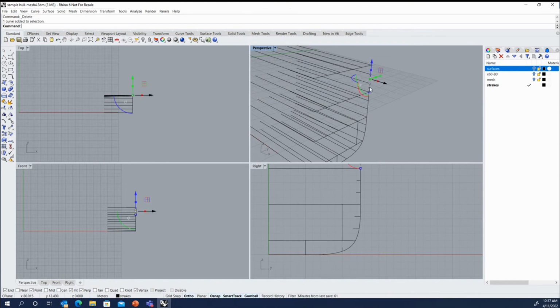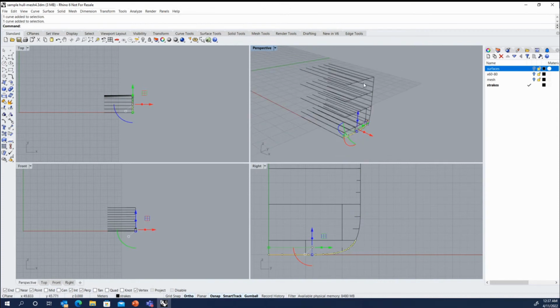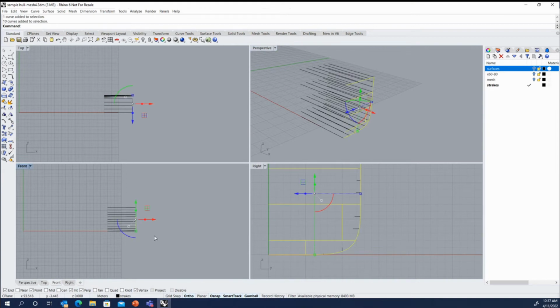But if I click on them, you can see the density of these curves is a lot greater than just the endpoints of those polylines, which is what I really need: a polyline consisting of only the points at those ends of the endpoint curves. So I can delete all of the curves from this end as well.